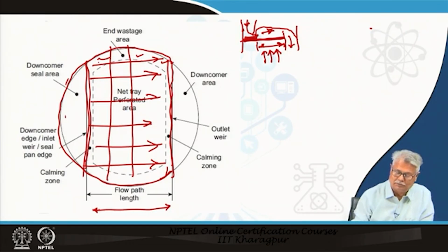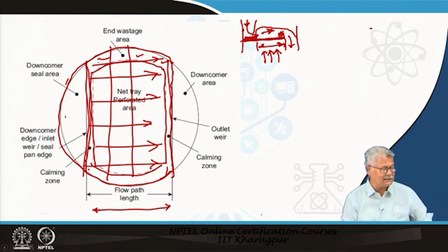Immediately after it comes out, you have a lot of turbulence. Quite possibly, you will not be placing here your vapor dispersers too close. So, quite naturally, what you have after it has come out from this is another zone where you do not put your vapor dispersers. Exactly in the same way, you will not be putting the vapor disperser right before your outlet weir. So, this central area is the area where you have either the sieve holes or the bubble caps placed, or the valves being placed there.